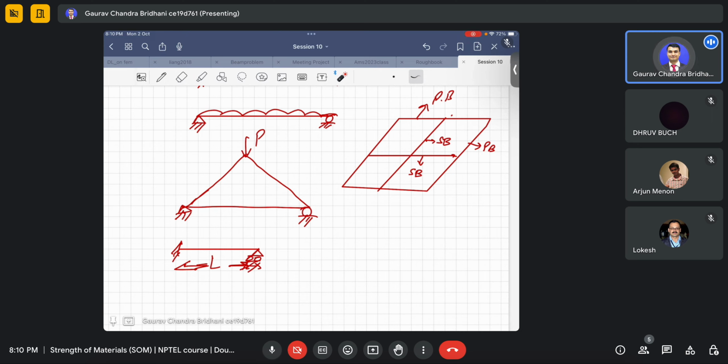So there are some materials, mostly called bearings, their general term is bearing, and they're elastomeric in nature, meaning they absorb load and then distribute that load. So those elastomeric bearings are provided. The bridge deck or the box girder is in contact with the bearing, and then the bearings distribute the load. Now there are different types of bearing also.